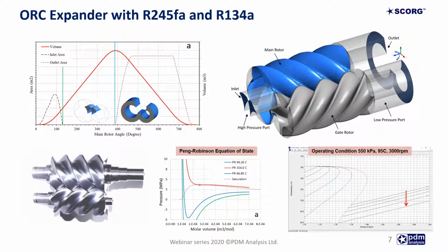In this example, we have used different equations of state such as the Peng-Robinson, Redlich-Kwong, and Soave-Redlich-Kwong. And in addition, also the REFPROP database can be coupled directly with the flow solver in order to see the accuracy of the solution.